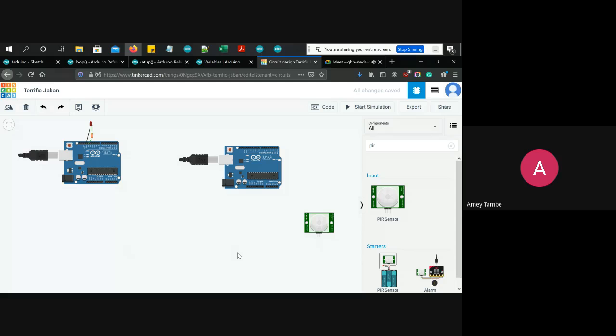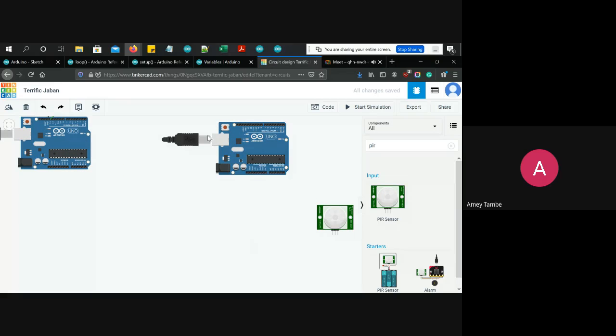In order to connect our PIR with the Uno, we need to click on the pins of the PIR. So this is the signal pin. If you hover your mouse, it will show you which pin it is. Like in our sensor, we need to see in the codes and the printed circuit which pin is for what. Similarly here they will be displaying it. So this is the signal pin, and the signal pin will go to 3. If you click on that, a wire is automatically attached to it.